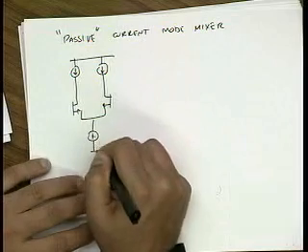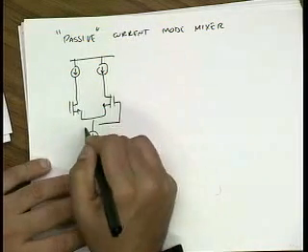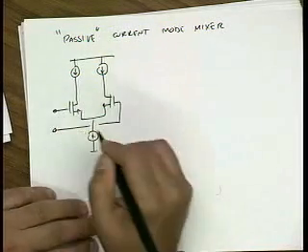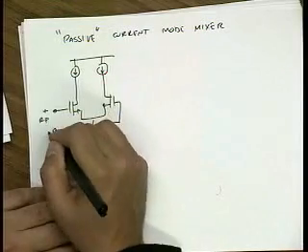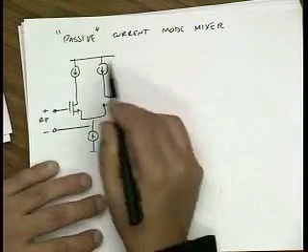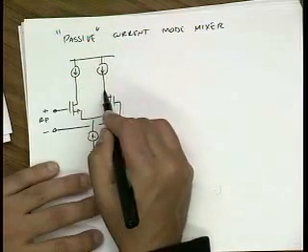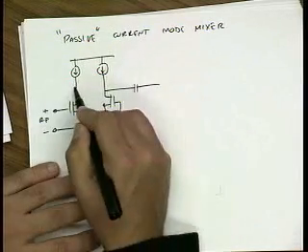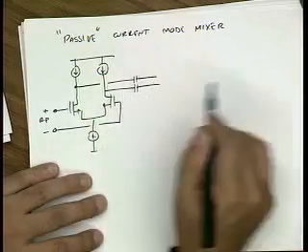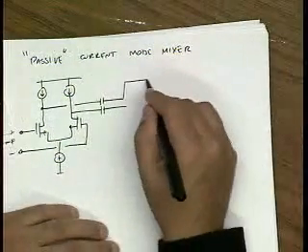So we're going to have some input transconductance stage to convert our voltage into a current. I'm going to have a high impedance load, so basically I'm going to push all my RF current into the mixer.